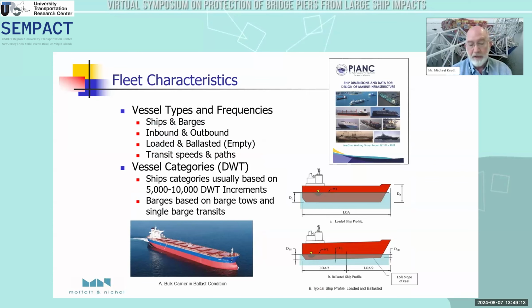The AASHTO guide specification is over 33 years old, and so vessel types have changed quite a bit since then on the larger end particularly. The upper right is a recent PIANC publication on ship dimensions and data design for marine infrastructure. This is a good resource now for vessel types and shapes, and is what we use when we do our analysis. I wanted to highlight here, though, that ballasted vessels are critical in the analysis.